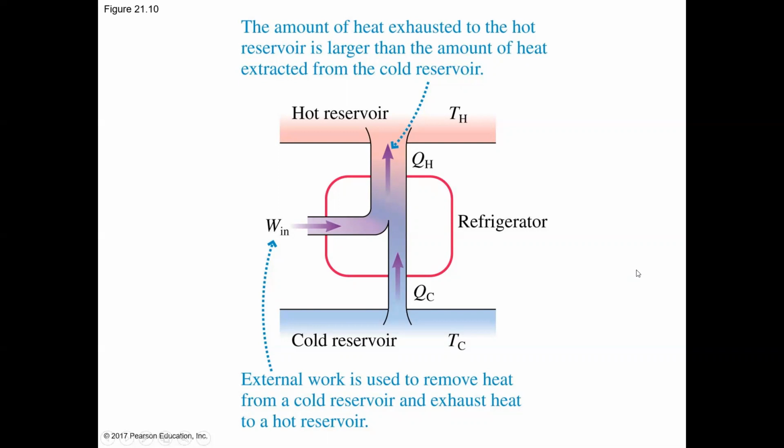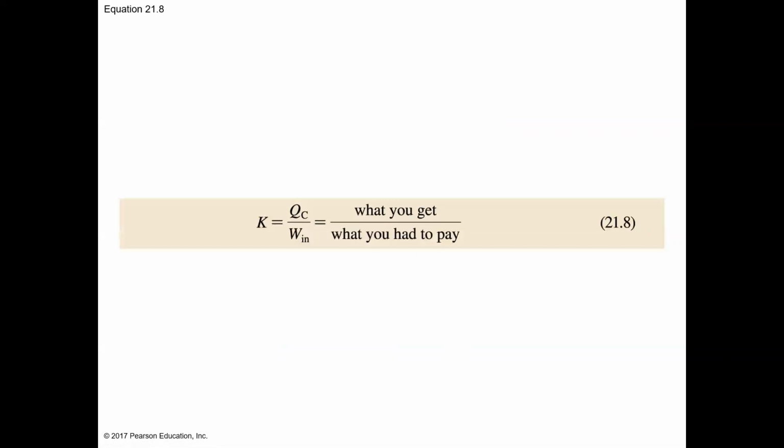Now, because of the different purpose, your book introduces a slightly different definition for the coefficient of performance. And this is where the mistake comes in on the part of the solutions manual. If you read the problem in the book, they give a new definition for the coefficient of a heat pump. But then the person who wrote the solution disregards that definition and continues with the original definition. Again, here's the original definition, because the whole point is to scoop as much heat as possible out of the cold reservoir in your freezer box. That's why this is a sensible definition for an actual food refrigerator or freezer. But now the objective is different. The whole point now is to scoop as much heat as possible into the hot reservoir, which is your home.